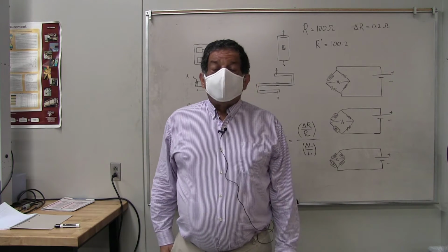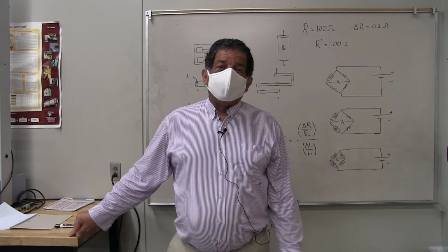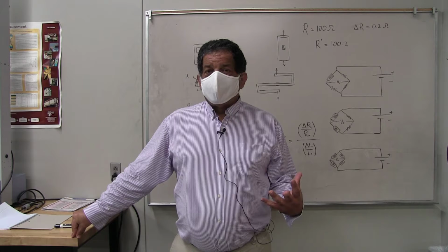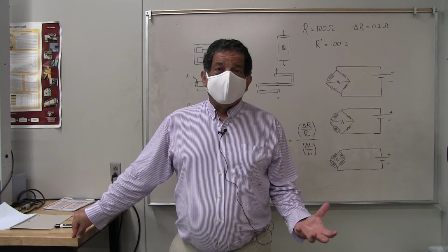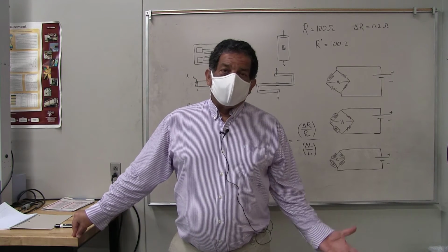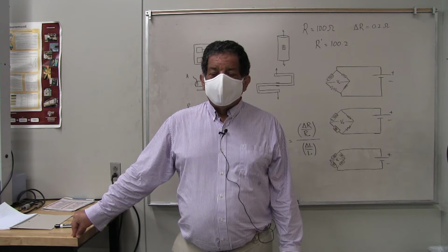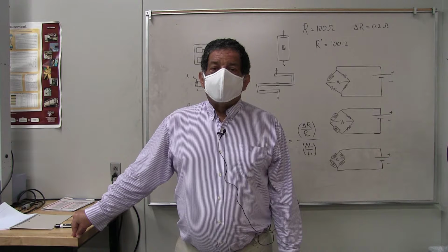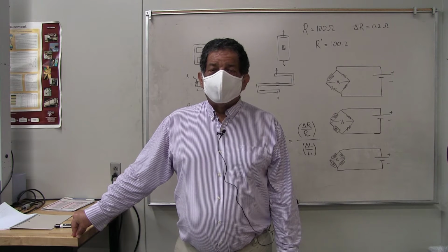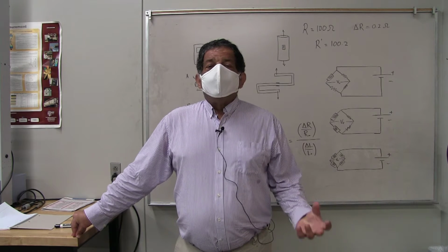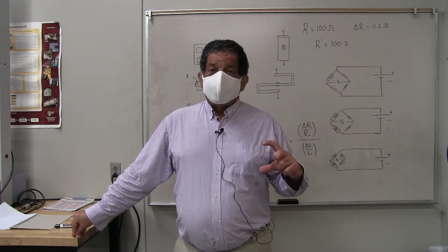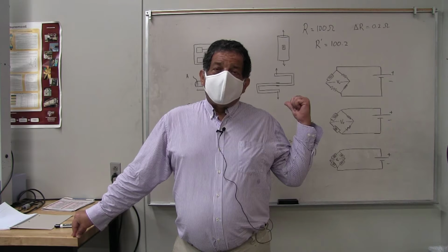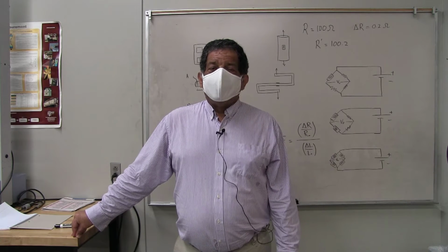And in order to get real world data, you can do all the modeling that you like, but unless you have high quality data about what forces the axle is actually encountering, your analysis is not worth very much. So as part of our attempt to get real life data for what stresses those truck axles were experiencing in the field, we instrumented the truck axles and the suspension with strain gauges of just the exact type that I'm going to be talking to you about today.